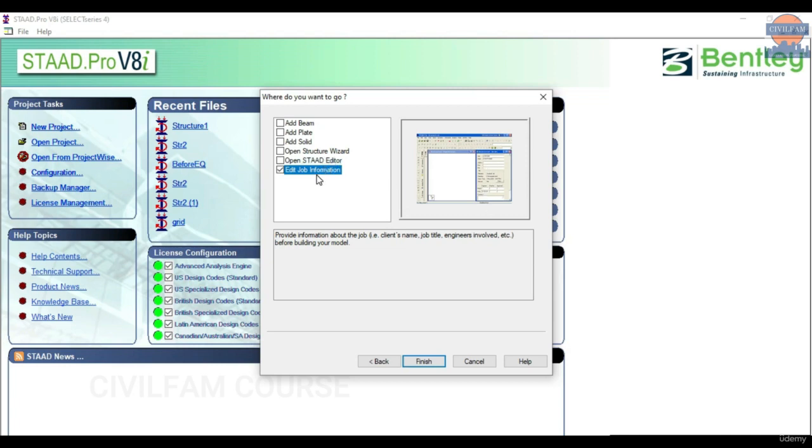In this case also, what I want to do is go for add beam. Your beam, column, everything will be considered as add beam here only. That's one very distinct difference between this and ETABS. If you click on add beam, your column, beam, everything will be considered as a beam portion only. But don't worry about it. It is just a name. Work-wise, a column will behave as a column, a beam will behave as a beam only. So don't worry about that. I hope you have understood.